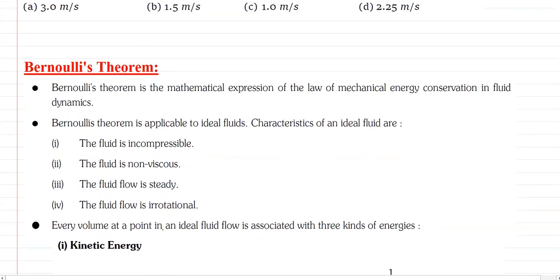There is another very important theorem to explain the properties of fluid dynamics. It's called Bernoulli's theorem. Bernoulli's theorem is basically a theorem of conservation of total energy, or conservation of work-energy. The conditions to apply Bernoulli's theorem are that the fluid is incompressible, the fluid is non-viscous, the fluid flows in steady state, and the fluid flow is irrotational. That means this is completely streamlined.